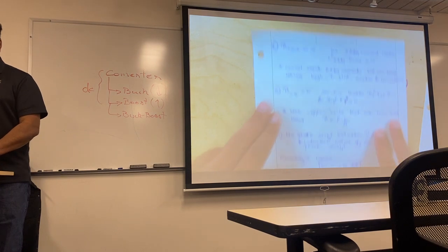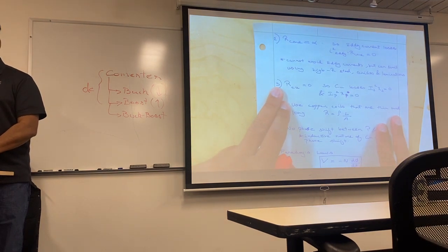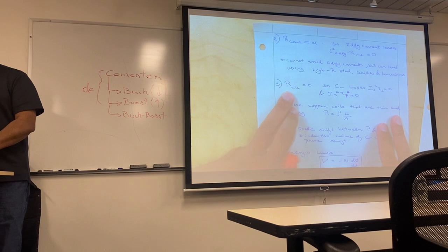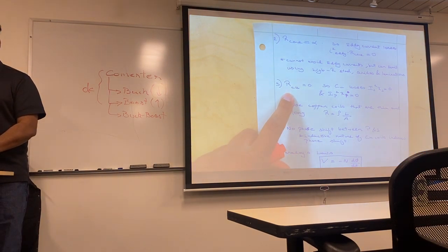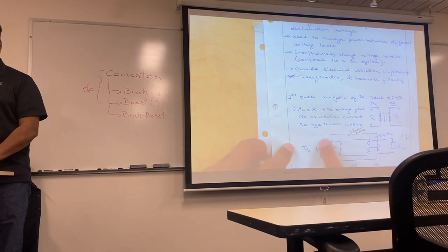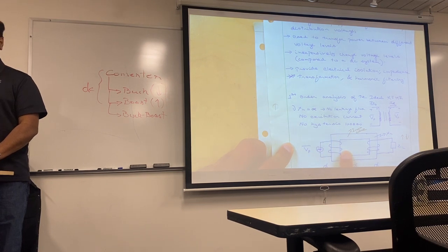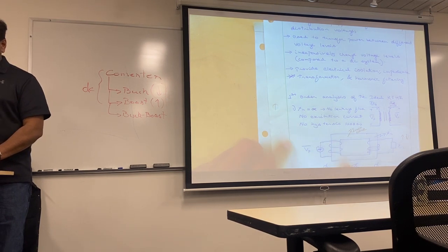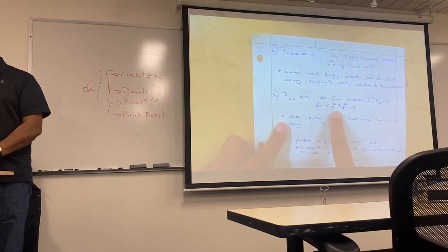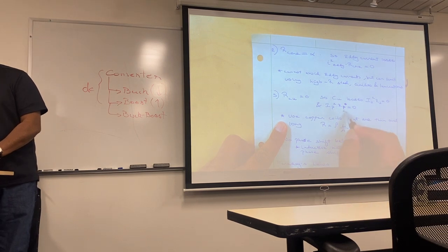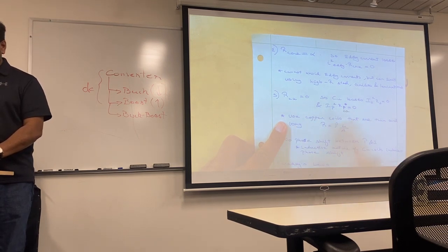The last thing I'm going to assume is that the resistance of copper is zero, which is an absolute lie. What I'm trying to do here is, I have copper winding here. I am trying to say that there is zero loss here due to copper, or a heat loss. So the formula for heat loss is I squared R, and because it is copper, I squared R copper, I'm assuming it is going to be zero.